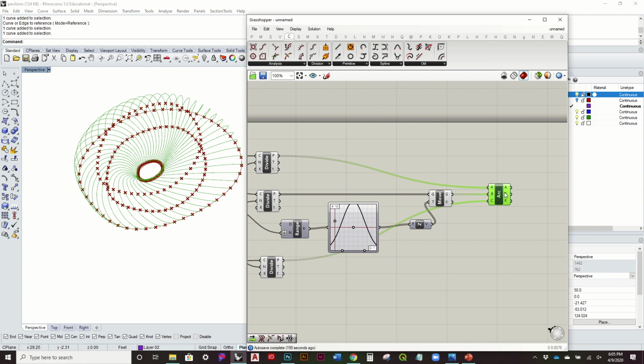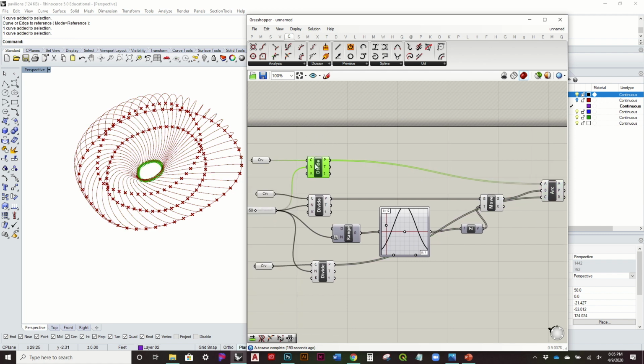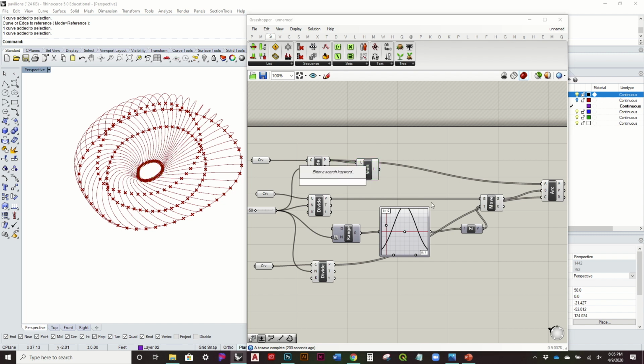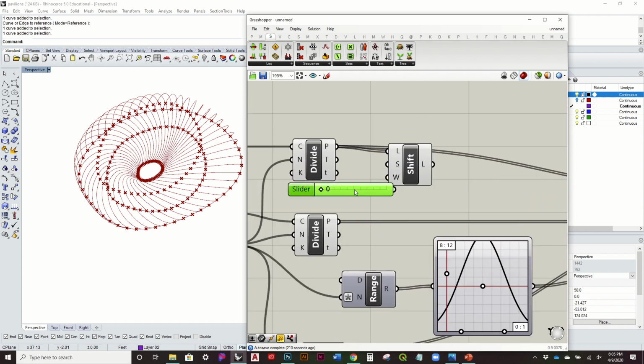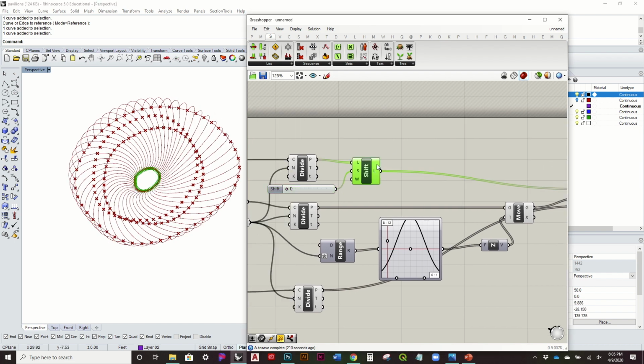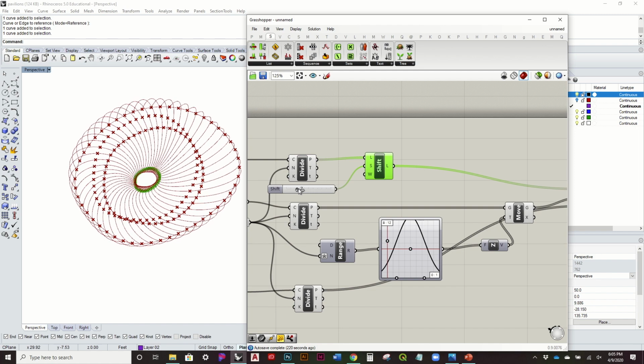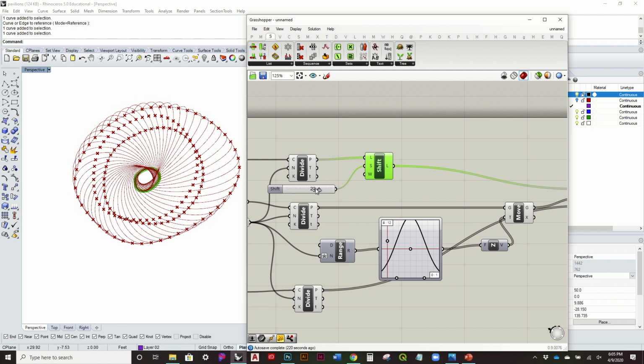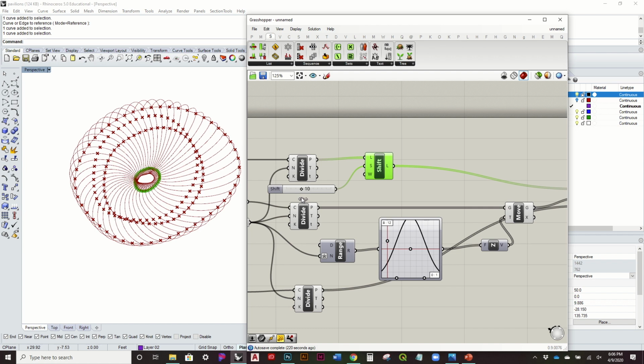So if we wanted to twist a little bit, I can take the points, in this case the inner ones, and let's go to sets, list, and shift. So again, I'm going to just pick some value, maybe like 0 less than 30, to not get too crazy with it. And that'll be re-input into there. So you can see as I start to twist that around, I get all sorts of different angles. You might get something really weird, so be careful with that.